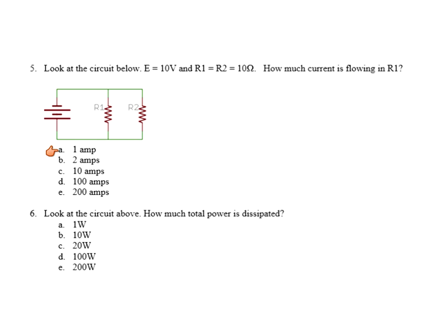And look how easy the math is on these. A lot of times you don't need to use your calculator, but if you want to make sure, use it. Sometimes you don't want to run into the situation where you guess with the math in your mind. Do the math if you have to. It's okay. Now look at the circuit above. How much total power is dissipated? Well, if in there we have 1 amp, how many amps has to be flowing in that one? Well, they're both 10 ohms, so what do we have? We have 1 amp here. We have 1 amp here. So the total current is going to be what? It's going to be 2 amps.